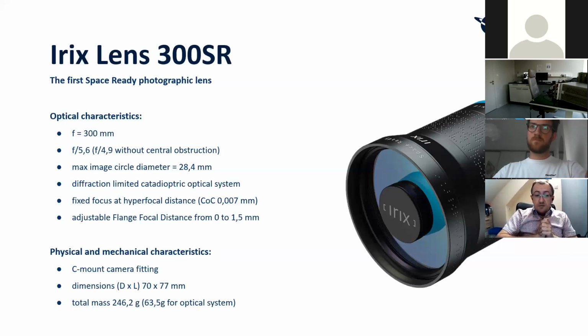After a few months of optical design, we got a sketch of the lens, which represents very good optical resolution. After our test with a color Bayer sensor, the lens provides more than 50 lp/mm at this moment, but this is still subject to update.